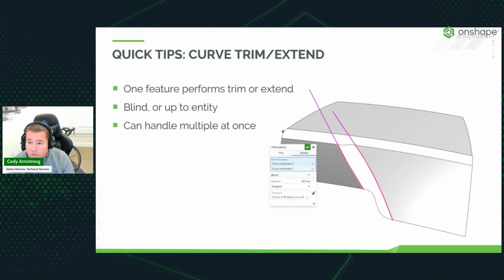One other neat thing about the trim curve is you can build design intent. You can say this is trimmed up to an entity. And so I can extend a curve up to a face or up to another point.